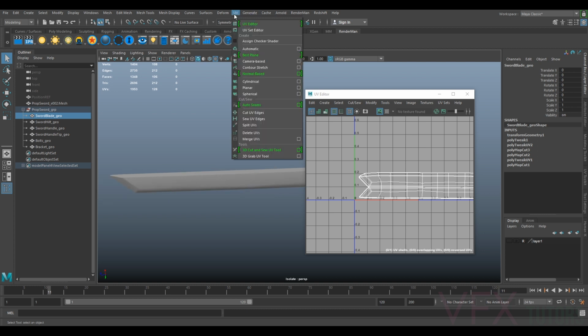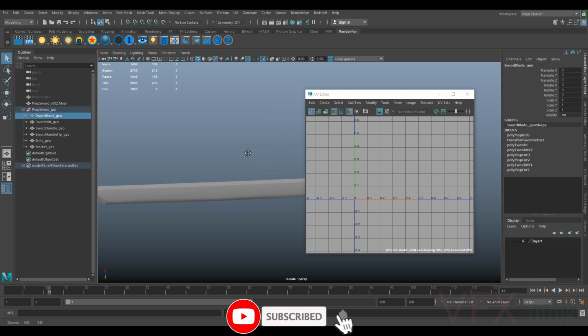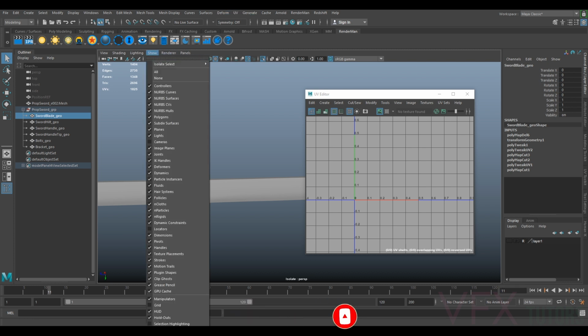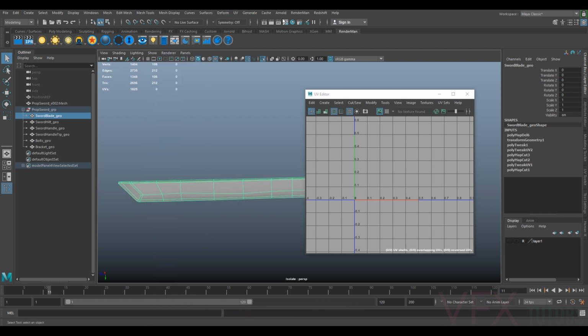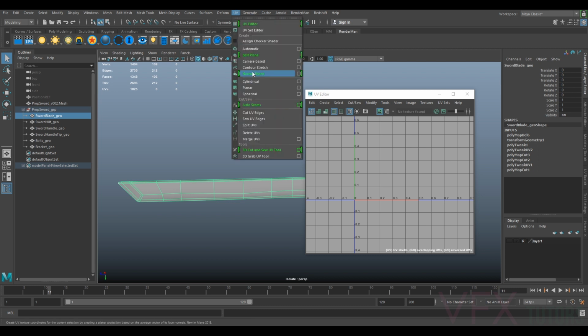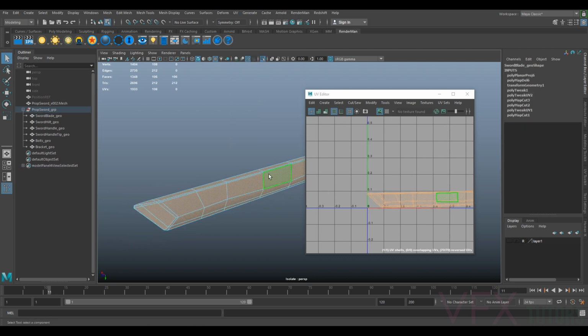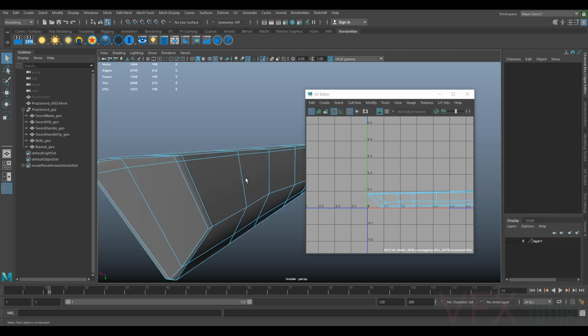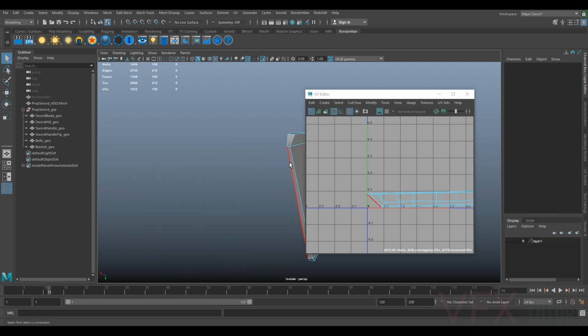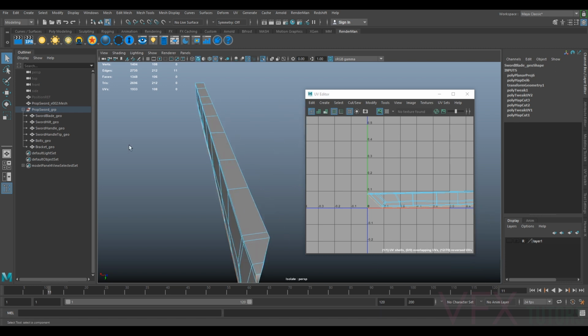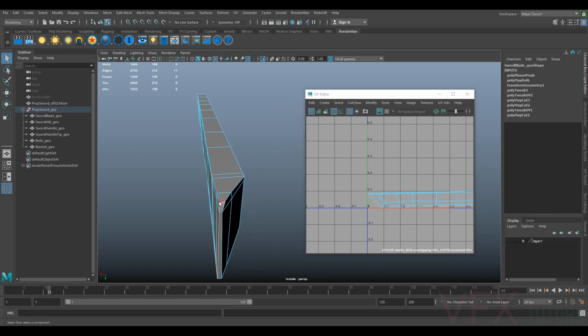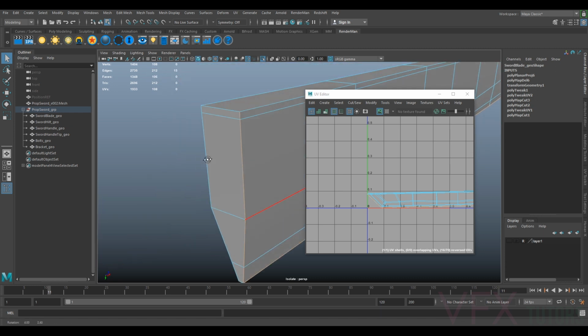So I'm just going to actually UV, delete UVs, select it again, and go, I've got show selection highlighting off. Go UV camera based. I'm going to select the edges. And I'm going to double click on this edge. And that's gone up to that corner, which is fine. Because we don't want to have a seam across here. Because it's just easier to fix it this way.